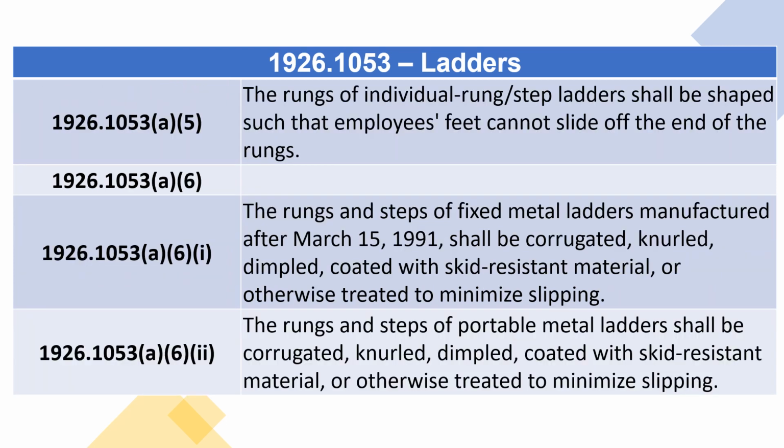1926.1053(a)(5): The rungs of individual rung/step ladders shall be shaped such that employees' feet cannot slide off the end of the rungs.